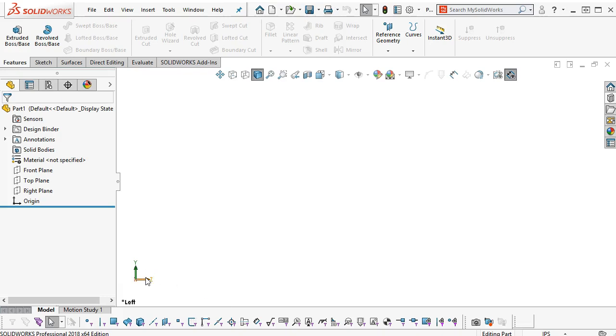When I go to the right, now we're looking at YZ, horizontal, vertical, and then to the top, X and Z, horizontal, vertical, and Control 6 is the bottom. Control 7 goes to isometric, and we could be any one of those depending on what we selected. So front, back, left, right, top, bottom, isometric, and then number 8 is normal to. All right, so we'll get those straight.